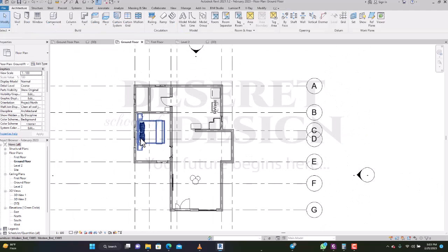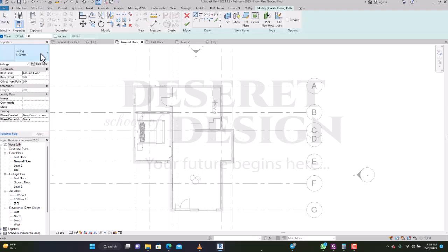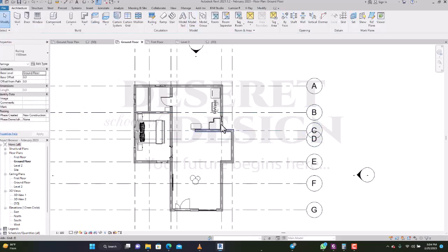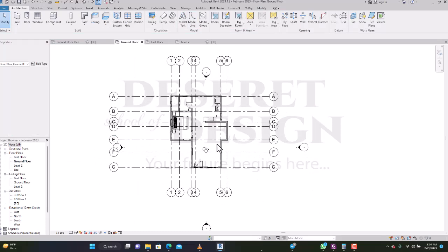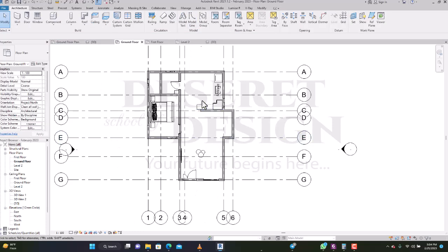So anytime I draw a railing and I want it to look like a handrail, then I'll just select it in my project. So if I go to railing, now if I go to my drop, you see the handrail I brought. This is it. It's inside. So you just choose how you want your railing to look like. Then just choose to replace it. So that is the way to go about the railing too. Any other question?